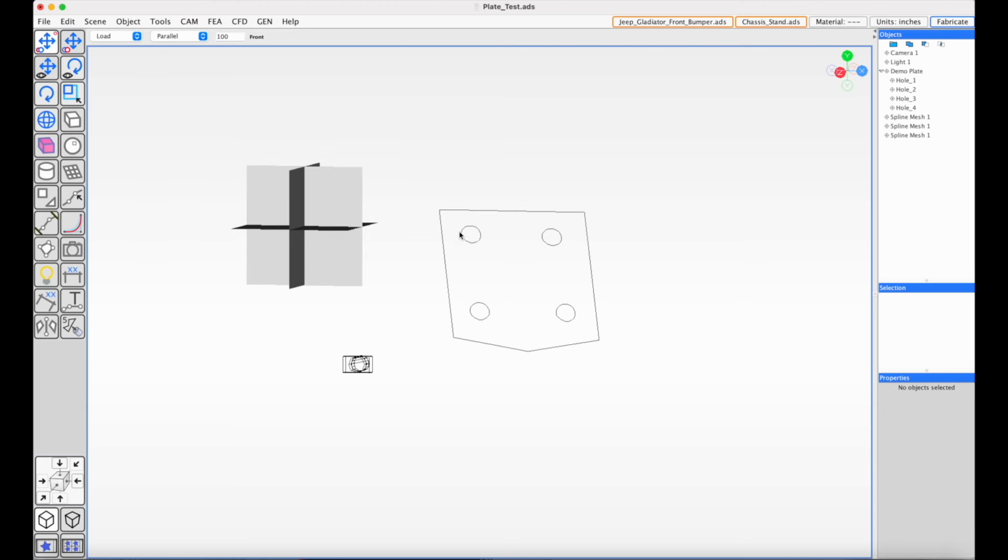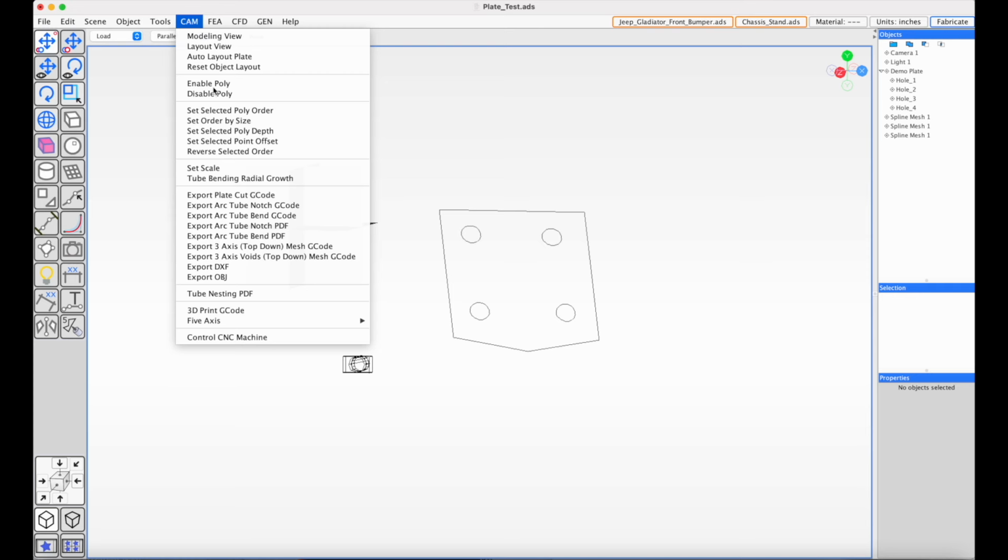In some cases, if there's a lot of material removed from a part, there may only be a small amount of material holding the rest of it on, and you may want control over which pieces are cut so that you can cut a smaller piece and then cut a larger piece later, just so that you have control over how much material is connecting the remaining metal.